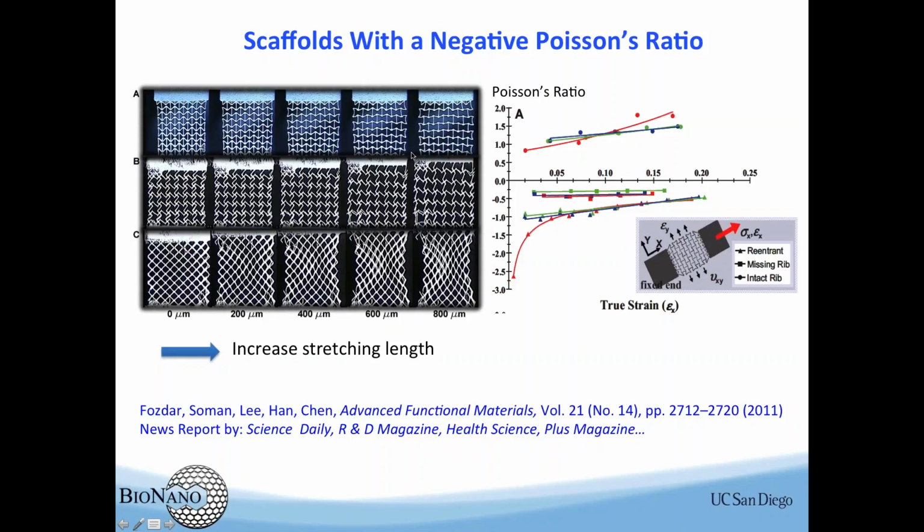Okay. So the reason you can have this kind of negative Poisson ratio property is because of the microarchitecture of the material. So if you have pores shaped like this one or this one, then when you stretch them, they actually expand. For traditional material like square holes or circular holes, when you stretch them in this direction, they can become smaller, and eventually break. Okay, so this is positive. These two devices are negative in terms of Poisson ratio.